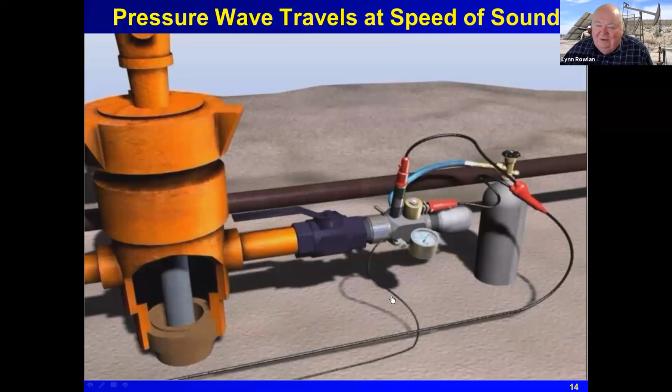And you always take 2 shots in the well to make sure that they repeat. And the software typically, by default, counts the collars. The collar echoes determine the number of joints to liquid. And that's typically how we, by default, determine distance to liquid level.